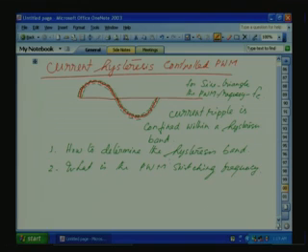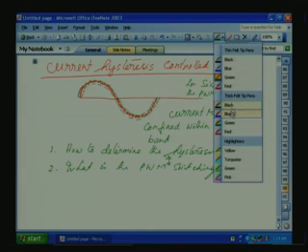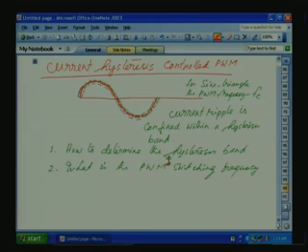So this is dependent on the hysteresis band. So we have to design our hysteresis band, these are related, depend on the hysteresis band, so that the switching frequency is controlled. Now this also depends on the type of load, load with inductive or load with back EMF load. So let us design, how to design the hysteresis band for a particular switching frequency, right? And what are the merits and demerits of current hysteresis controller. This we will study now.